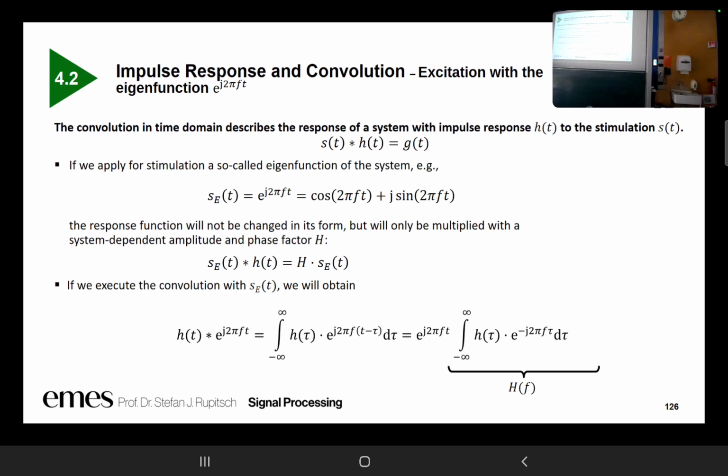It's not like in the case of operational amplifiers, where the decisive point is the gain bandwidth product. In this case, the time bandwidth product is decisive. A sinusoidal signal has an infinite time, but the bandwidth is 0. In the case of a chirp signal, you have a certain bandwidth and a certain time. But this is information theory, which goes a little bit beyond the scope of the section.